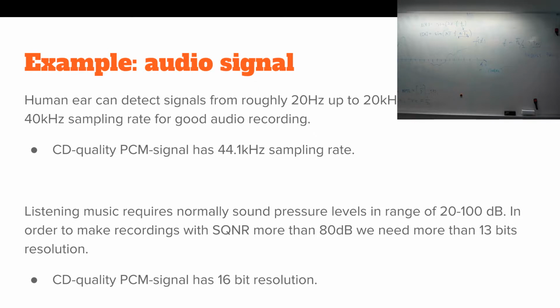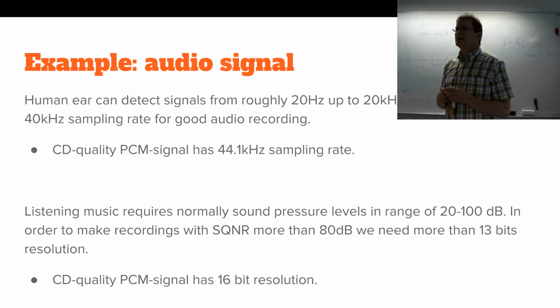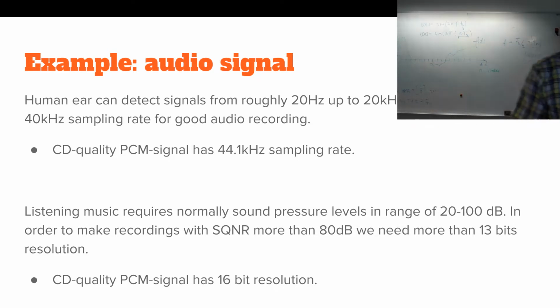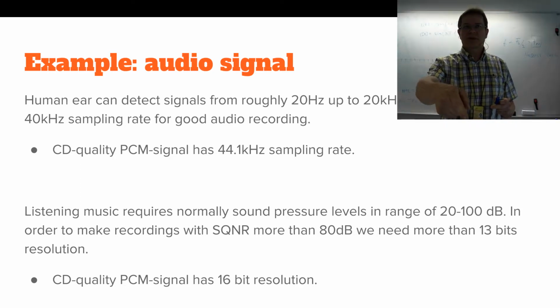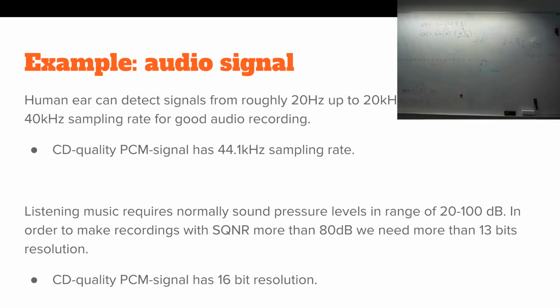These small microphones are usually ceramic microphones, and they are really good for ultrasonic sounds, or they are also really good at picking up all kinds of noise from the electronics. For example, this computer display has high frequency DC-DC converters to lift up their signals.